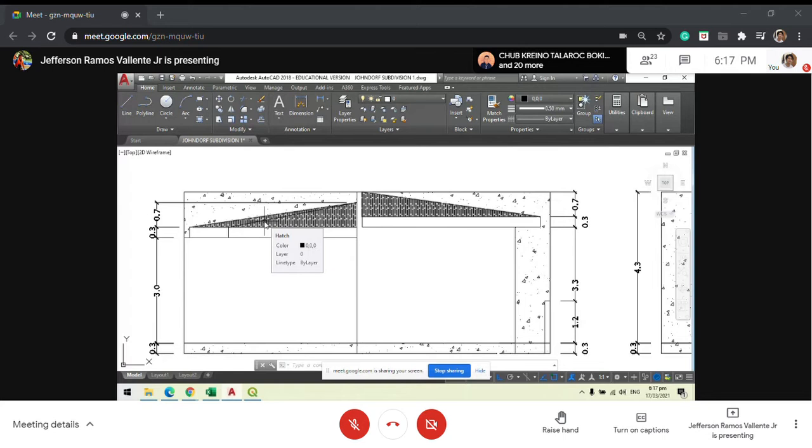Sir, how thick is a firewall usually? Firewalls are 0.25 meters thick. Thick na siya. Okay, usually, for small houses, there's no column. But if there is a column, you can go as small as 0.15 meters. That's allowed. Thank you, sir. Okay.